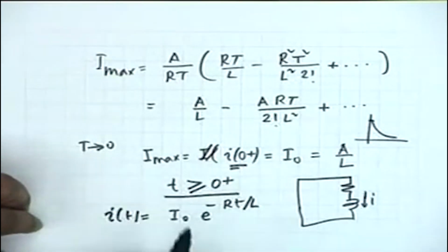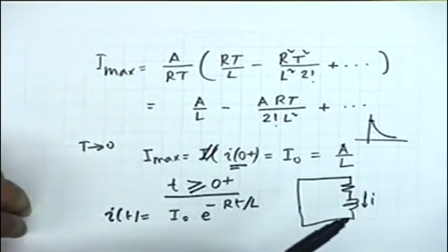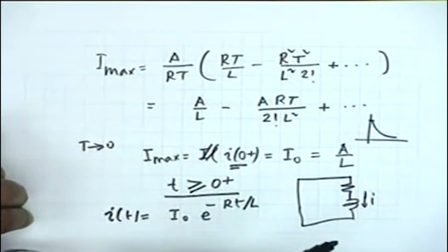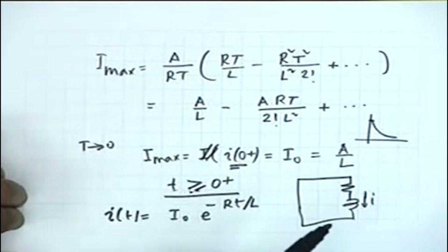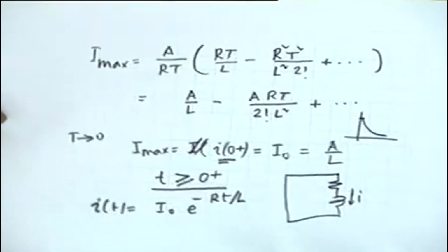This gives you a physical interpretation of the impulse function. What we did earlier was to obtain the impulse function as the limit of a pulse. What we have done now is to obtain the response to a pulse and then allow the pulse to become an impulse, and we see that the two responses are the same. This gives a physical interpretation to the question of impulse response.